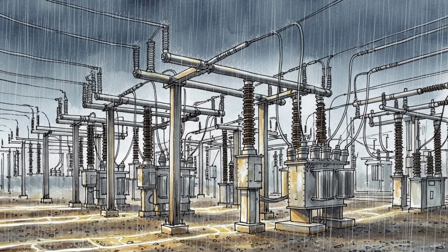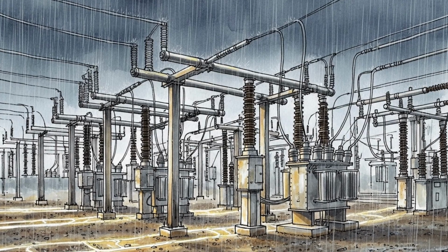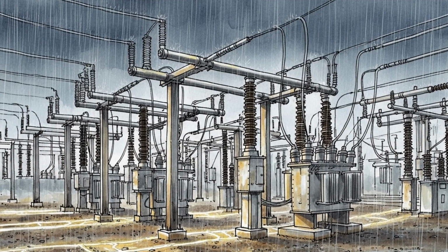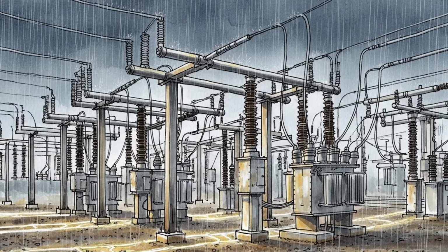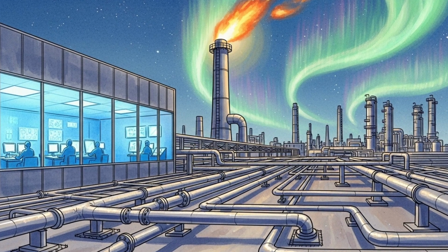During storms, operators of L-band and S-band systems raise link margins, lower modulation order and coding rate, and increase interleaving. Ground stations schedule more frequent passes and allow extra time for command and telemetry.